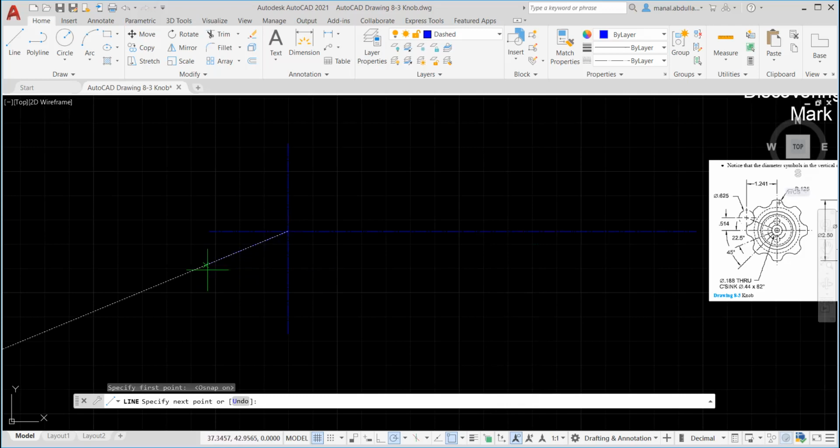Then you follow the reference lines to get this line on 22.5 and multiples of 22.5. Hit enter or the space bar to repeat and get this point. Now you follow the reference line and you get this angle. Also, let's hit enter again to repeat, and we need the 45 degrees. So we got here some construction lines. When we're done with that part, let's see here.